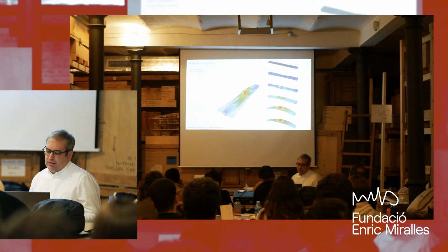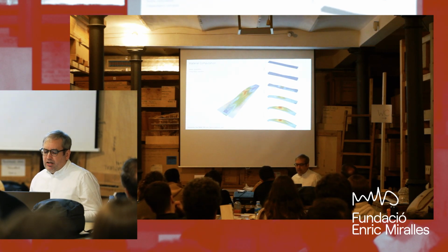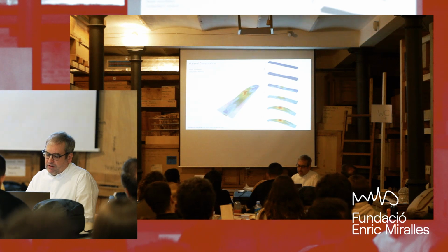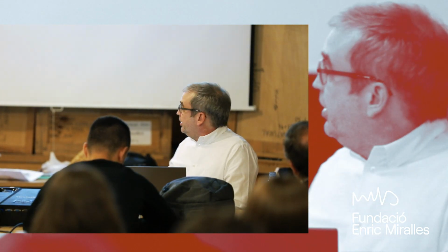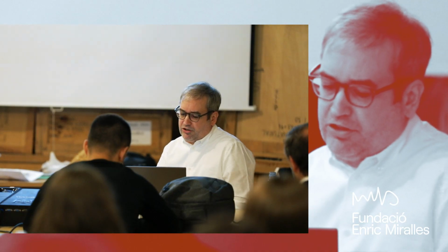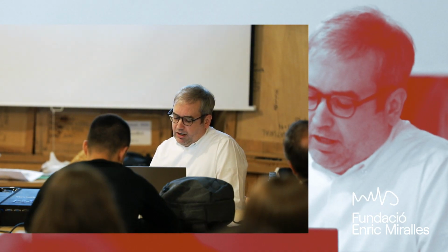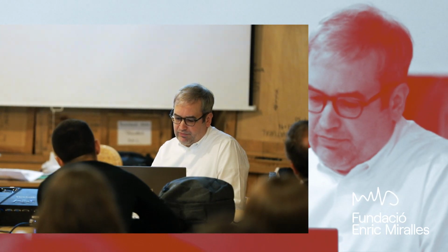And here we simulated this process of form finding or form generation, also this finite element analysis with Markus, which also visualized some of the stress points in the structure. So you can see in the lower part here that where the two strips are touching, there's a high compressive residual stress.